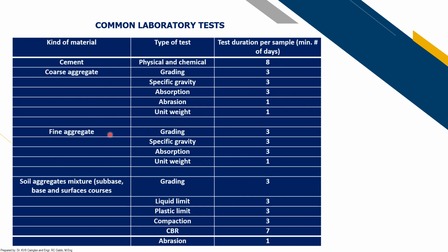And then for fine aggregates, if you submit a sample for your fine aggregates test, the test is the same as the coarse aggregate: grading, specific gravity, absorption, without abrasion, and then the unit weight. So the minimum number of days for the duration of the test is the same.